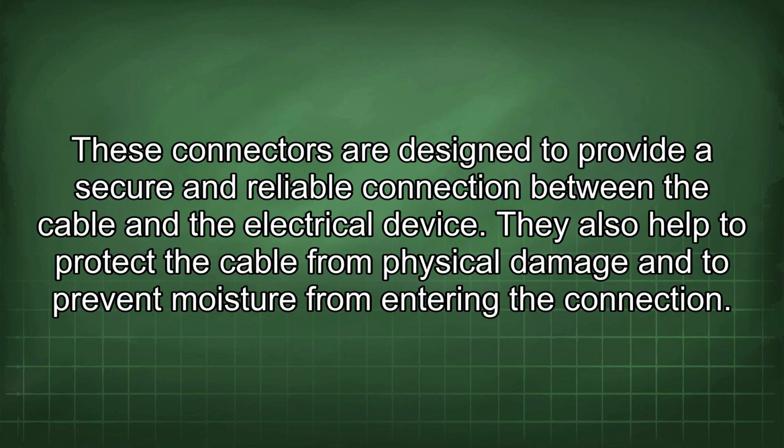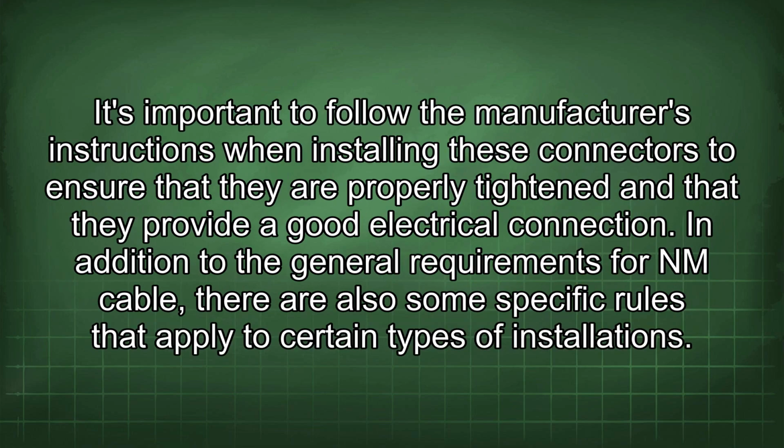When making connections with an NM cable, it's essential to use the proper type of connectors. These connectors are designed to provide a secure and reliable connection between the cable and the electrical device. They also help to protect the cable from physical damage and to prevent moisture from entering the connection. It's important to follow the manufacturer's instructions when installing these connectors to ensure that they are properly tightened and that they provide a good electrical connection.